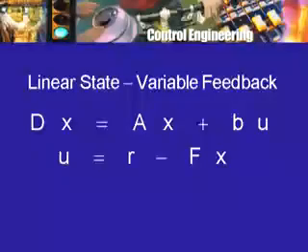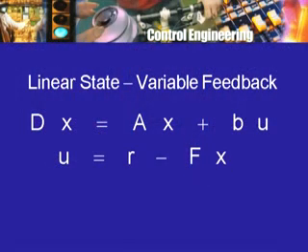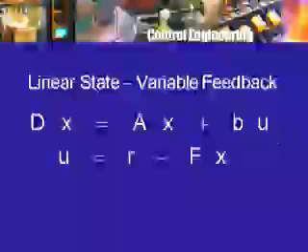Of course, this means that I have to measure the state variables, just as we had to measure the speed of the motor. Indirectly, of course, we did it by putting a tacho generator on the motor shaft. The output voltage of the tacho generator served as a measure of the speed of the motor. It was simply proportional to the speed of the motor. So, similarly here one will have to devise some physical system or set of components which will produce signals which are given by f x. So, this is the state variable feedback signal that is subtracted from the reference signal, and that is the output which is then applied to the system.